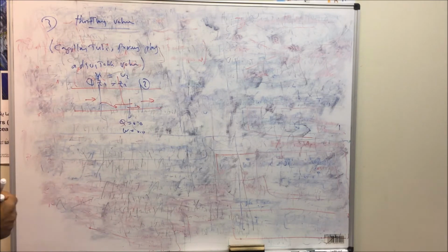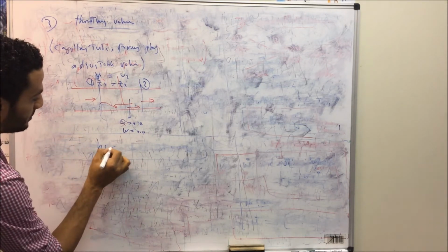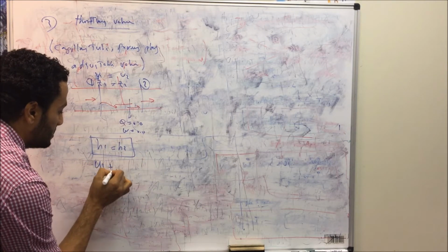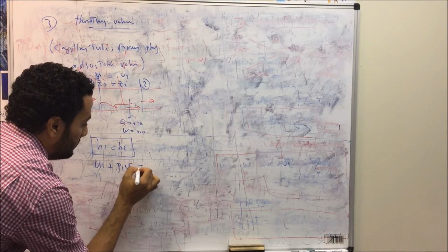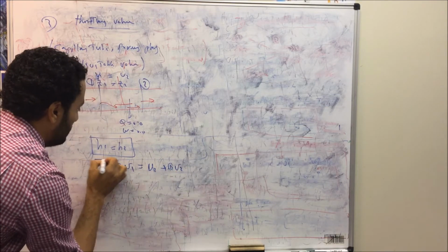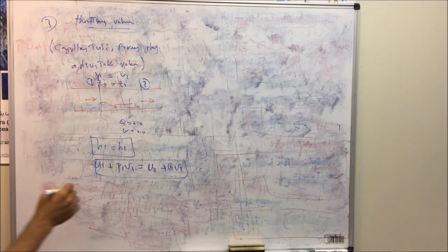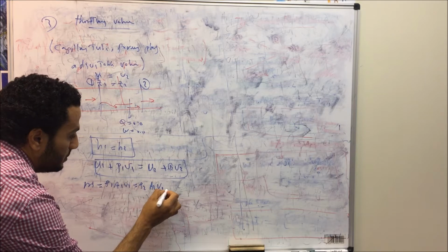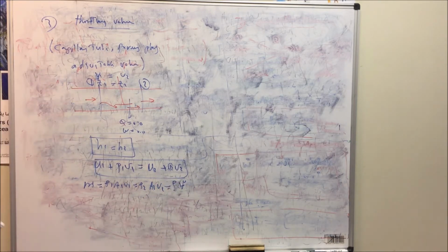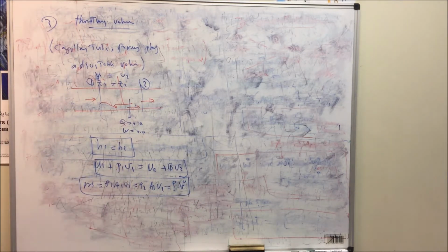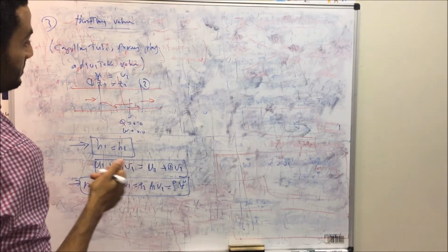If you reduce the energy equation in this case, you will end up with the enthalpy at inlet H1 being the same as the enthalpy at outlet, or we can say enthalpy is internal energy plus pressure times specific volume: U1 plus P1 v1 equals U2 plus P2 multiplied by specific volume v2. And the same mass equation applies: m dot equals ρ1 A1 V1, the same as ρ2 A2 V2, equal to the density multiplied by the volumetric flow. So this is the energy equation, and this is the mass equation in case we have a throttling valve.